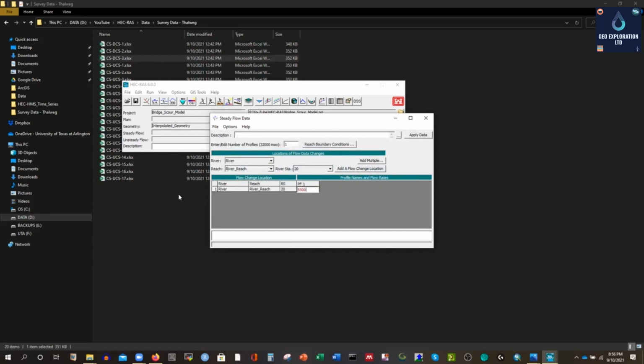If you have two rivers connecting together, or a different flow rate contributing, any tributary or distributary, you can add it at a specific section. If you have a tributary of a river at section number 15, you can select that cross section and add it. In a future video maybe I'll show that, but today I'm just going to show you a single reach and single simulation, then I'll add different conditions as well.